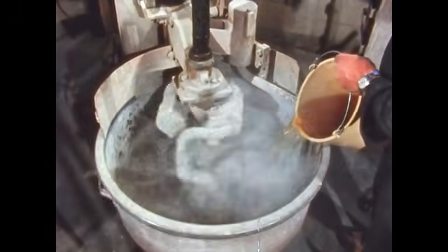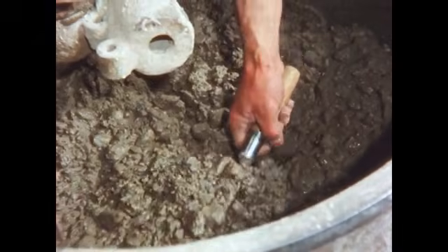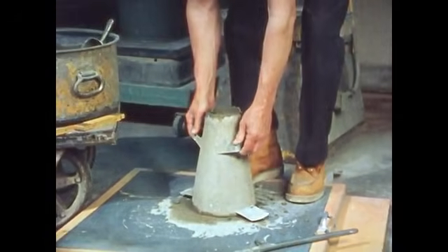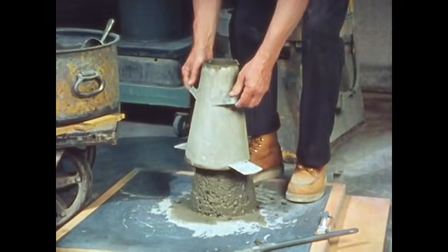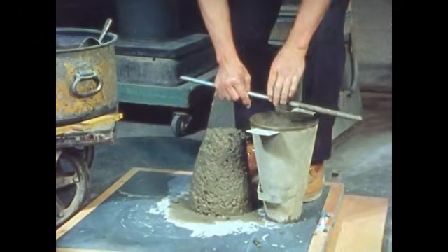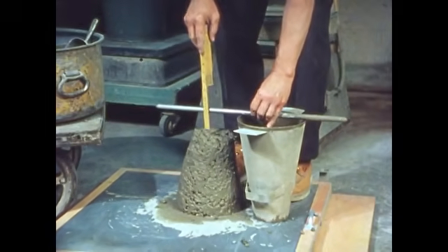All the cement is put into the mixer, then the water is added, and the two are mixed into a fluid cement paste. The coarse aggregate is added, then the fine aggregate. The two materials are added alternately until a workable mix is obtained. Not too grainy with coarse material or too mushy with excess sand. Standard slump tests are made during mixing until the right amount and proportion of materials have been added to produce the desired workability at the recommended slump of 3 inches.